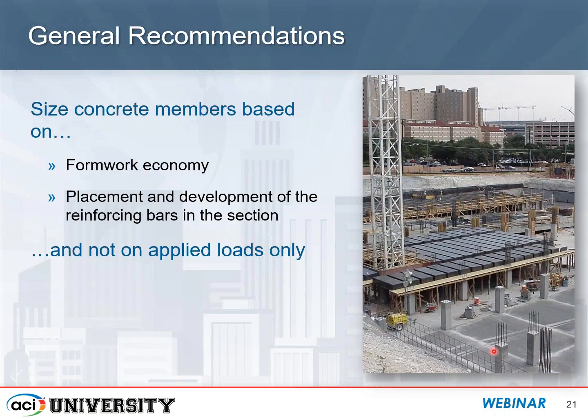Another general recommendation is to size the concrete members based on formwork economy, because as we know, that constitutes between 50 and 60% of the cost of the reinforced concrete structure, and also on the placement and development of the reinforcing bars in the section, and not just on the applied loads.